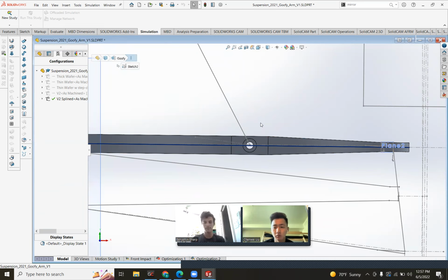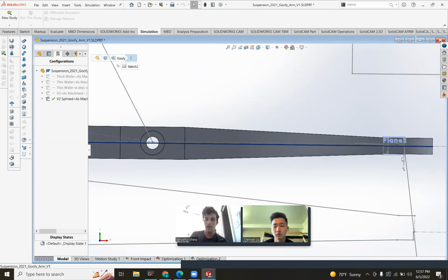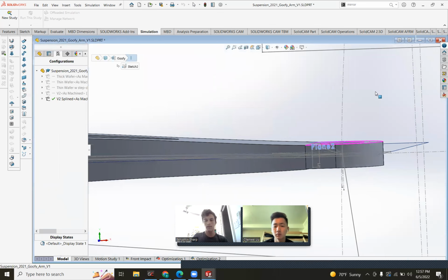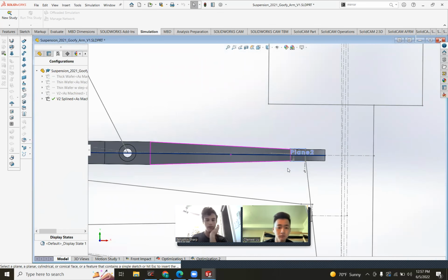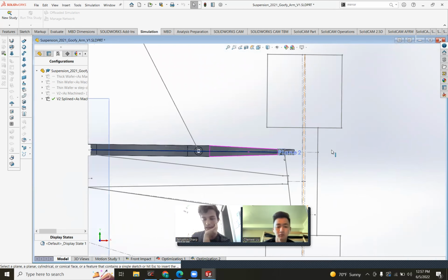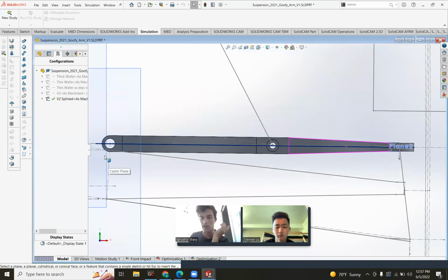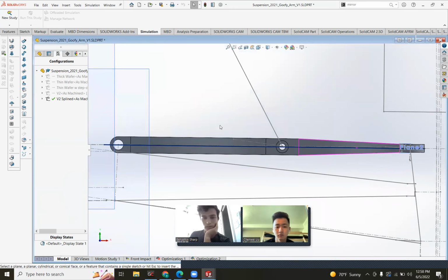That's the reason it requires at least a flip on a 3-axis or ideally a 5-axis CNC, that and the complexity of the bearing cup. But if you don't have a bearing cup, you should just keep this all the same thickness because you need a bolt hole here. And then it's a much easier thing to machine. And that's why the one we machined ourselves is all the same thickness.